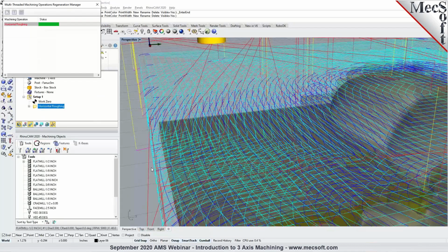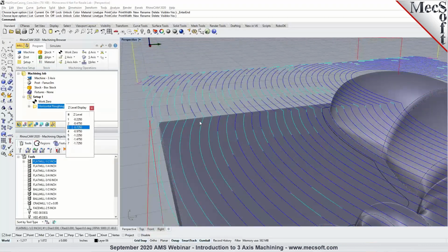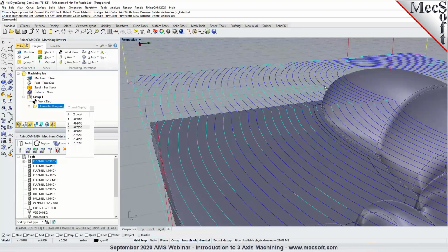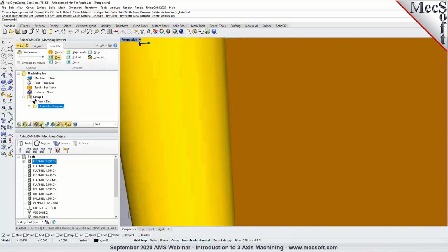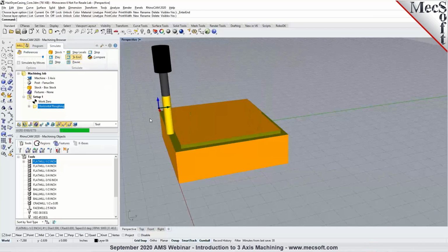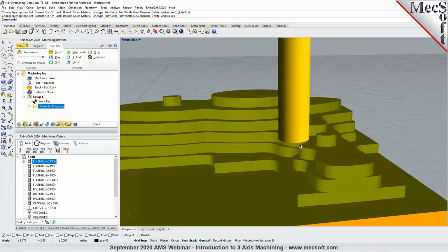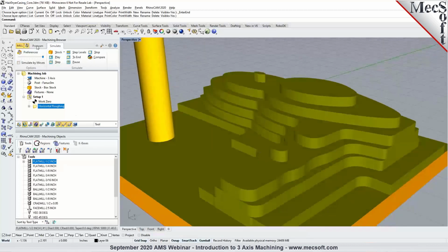So once the toolpath is generated, this would result in much smaller chord segments, and you can see the toolpath is much more accurate, maintains it within a tolerance of a tau. So let's go ahead and run the simulation in here. And I'm going to skip by doing a pause, then selecting Simulate to End. So we've now generated a roughing toolpath with a much tighter tolerance.